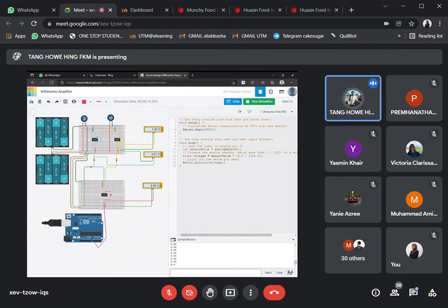So electricity comes to here and then flows into the voltage followers and then later on comes to here. It goes to the multimeter and then goes back to the ground and then the battery ground. So that's why this forms a complete cycle, starting from the power supply, going through all the components and eventually going back to the ground. It's a complete loop. So that's why the multimeter is able to give you readings.